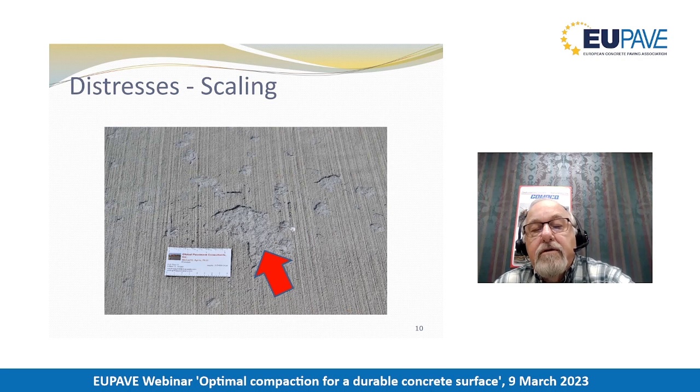In the first season where freeze-thaw damage occurred, the vast majority of the airport experienced this type of distress. Because of the FOD that's generated, you really can't operate flights on this, because of the opportunity for this material flaking off to be ingested into the jet engine. So this is a bad situation.